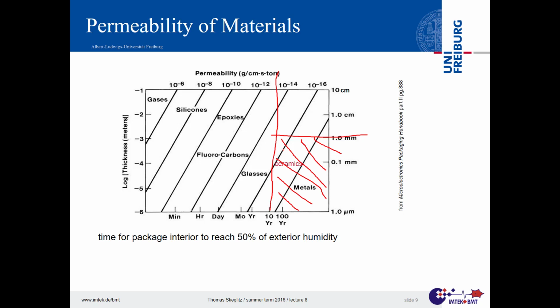If you go into different textbooks, you might find that permeability is probably not in old style torr, but in hectopascal or whatever. So the factor might vary a little bit, but the general principle is the same. And the definition of leakage rate over time, so hermeticity, is less than 10 to the power of minus 9 millibar liter per second.